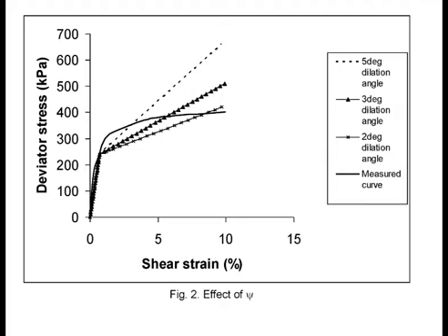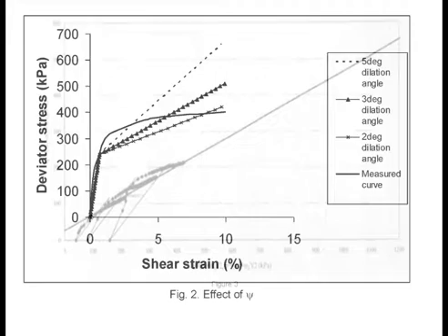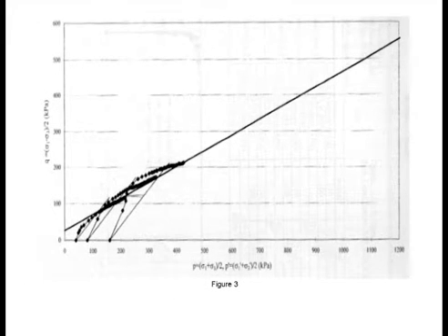Are you referring to this point? This point here? That point and this point, you mean? Okay. How do I get this point? This is the U point that I deduce from the stress path. Okay, I'll show you the stress path. Now, remember I told you about the stress path. I actually use the stress strain curve corresponding to this sample. And you can see the stress strain curve tells you that at a Q of about 110 kilopascal, S of about 100, T of about 110 kilopascal, the thing turns over.